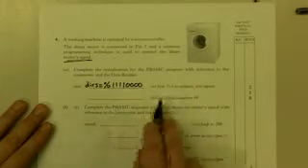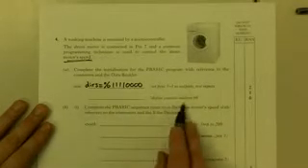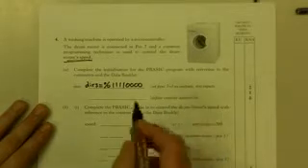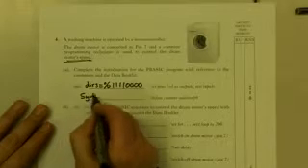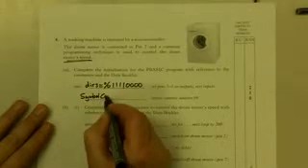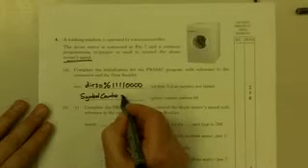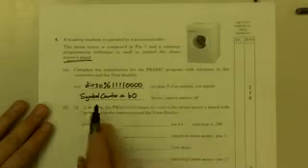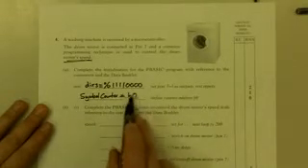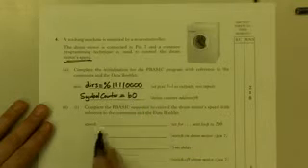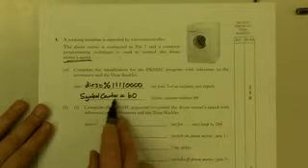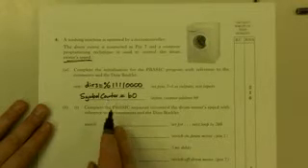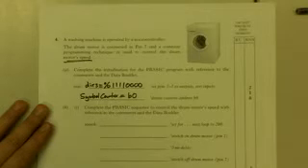So next line, define counter address as B0. Well, the command is symbol counter equals B0. Now you don't need to put this, you could just put B0 straight into the program for your for next loop, or you could define B0 as equaling the word counter. So you just substitute in the program the word counter for when you would normally put B0.